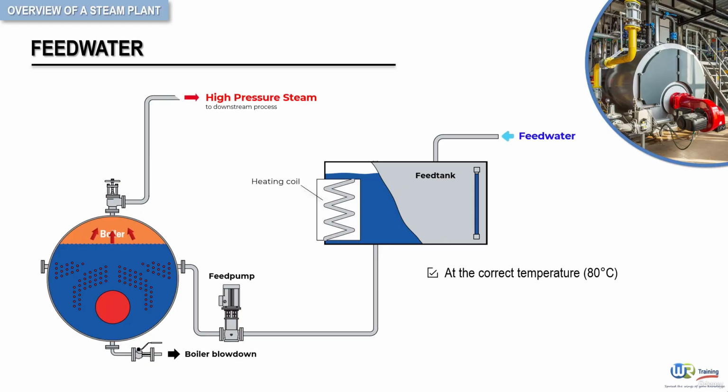The water must also be of the correct quality to avoid damage to the boiler. Ordinary untreated potable water is not entirely suitable for boilers and can quickly cause them to foam and scale up. The boiler would become less efficient and the steam produced would become dirty and wet. The life of the boiler would also be reduced. The water must therefore be treated with chemicals to reduce the impurities it contains.